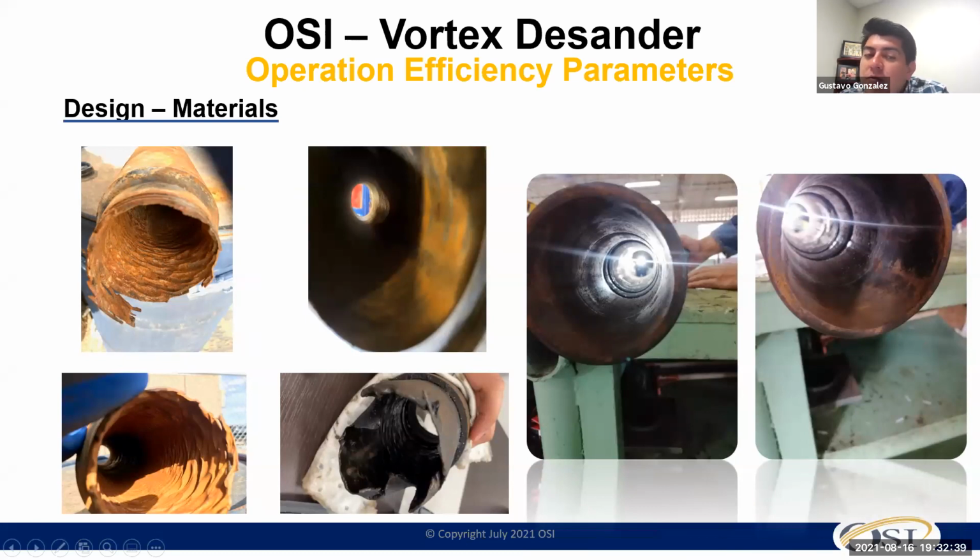This can happen, that you actually cut that housing or cut that desander. That's why you need to be sure, or if the force is too high, like in this picture, the operator actually cut the first tailpipe joint that was below the desander. That means that the helix was too small, and it created too much acceleration, so the sand was able to travel more than 4 feet, and high erosion started happening at this point. And that tailpipe is not normally designed to handle erosion, so it becomes a weak spot.